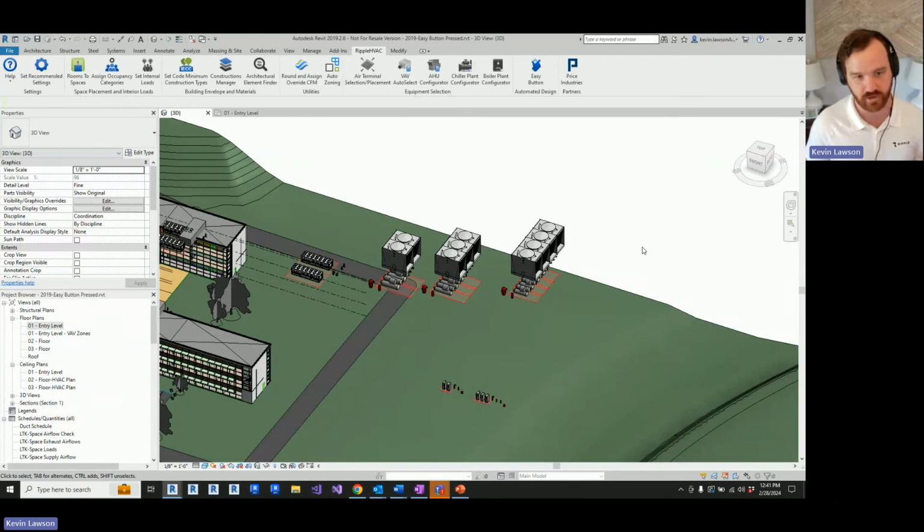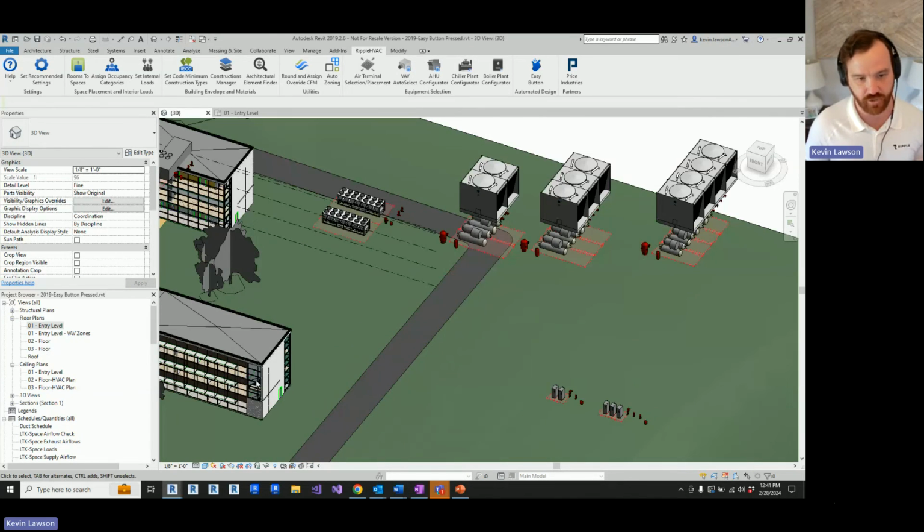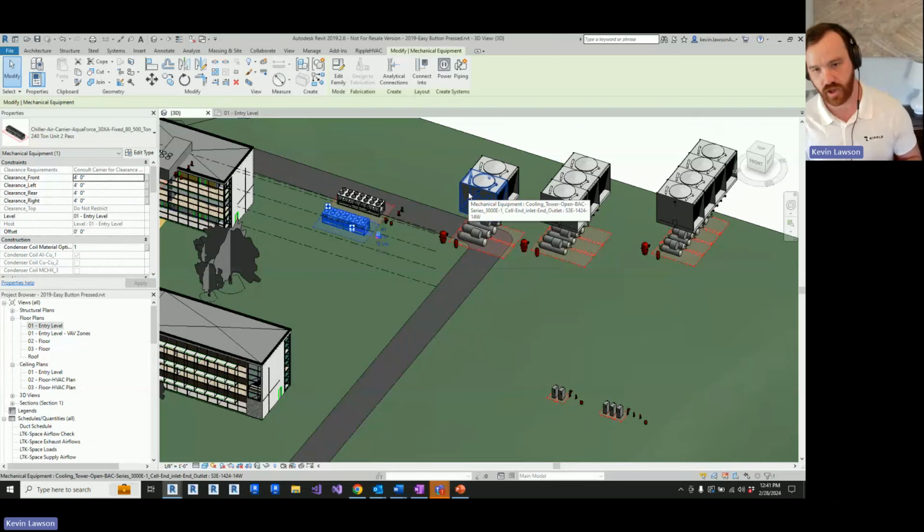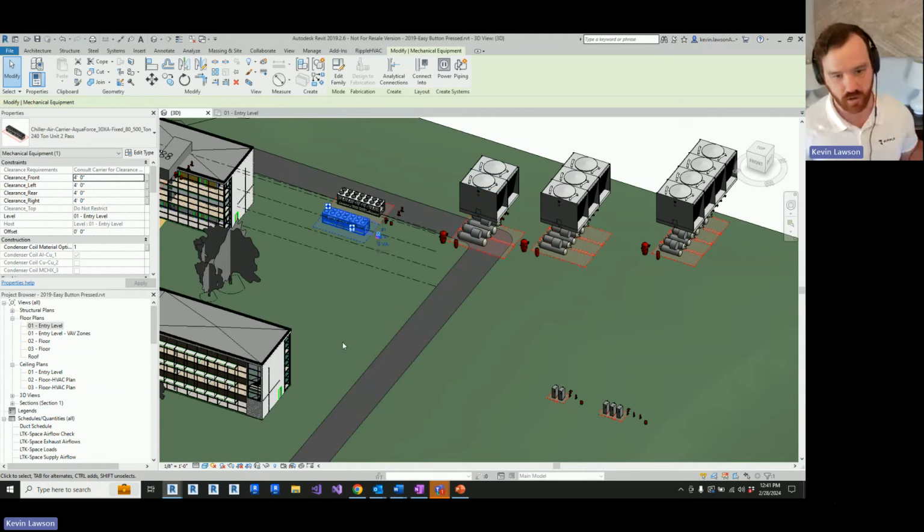What I've typically found is those things kind of cancel each other out. The problem that I always see is that somebody takes a factor of safety on the U value, and then the engineer that looks at the airflows takes a factor of safety on the load, and then whoever sizes the equipment takes a factor of safety on that, and the equipment just gets way too big. So taking a little bit of diversity after you took 5 factors of safety isn't very helpful. The goal is everything should be trackable. This load corresponds with this piece of equipment size. But yes, short answer is it's the sum of the peaks.